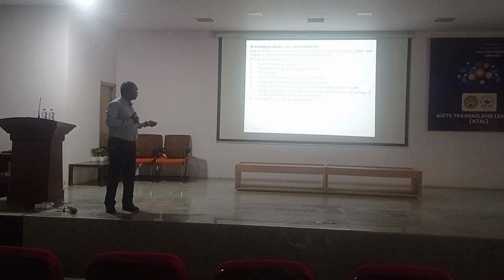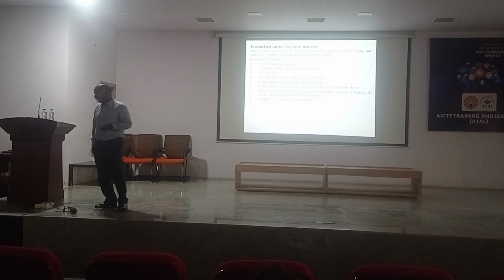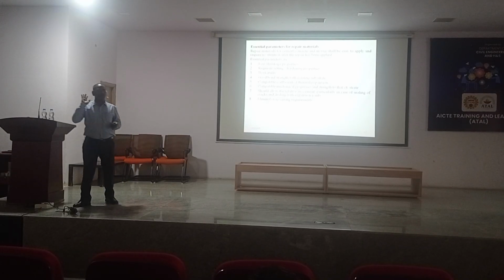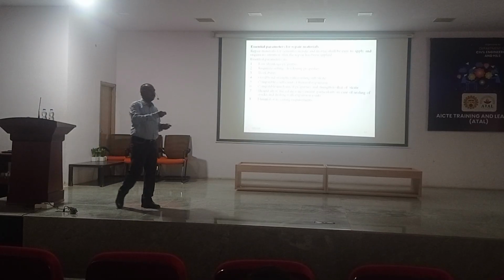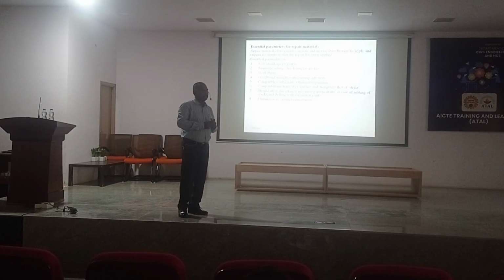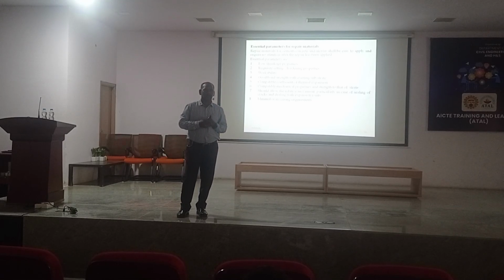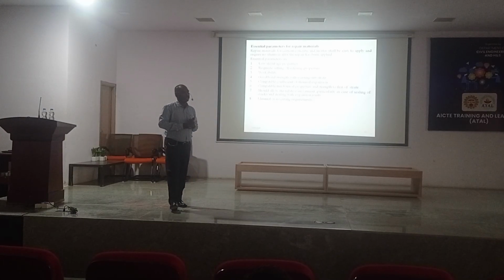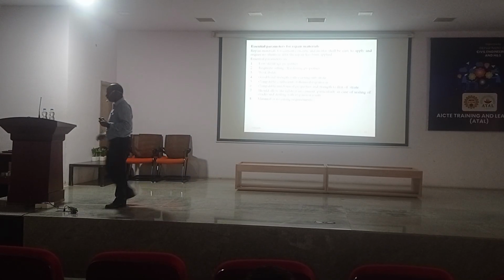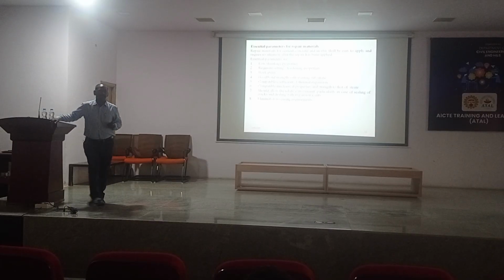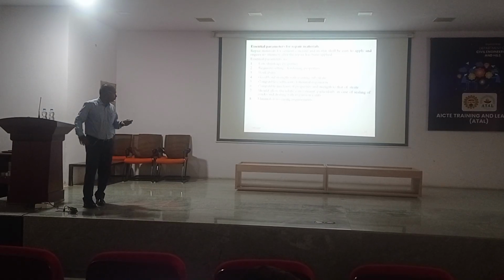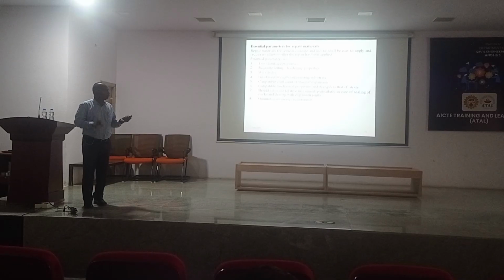And yes, this is also very important. The repair mortar should need minimum or no curing. It goes on curing for 28 days. What is the use? You can go for minimum or less curing, because nowadays self-curing agents are also available. You can go for self-compacting, self-curing mortars, which are also available. You can go for chemicals like PEG, polyethylene glycol, which is a self-curing agent. Go further, depending on the site conditions.